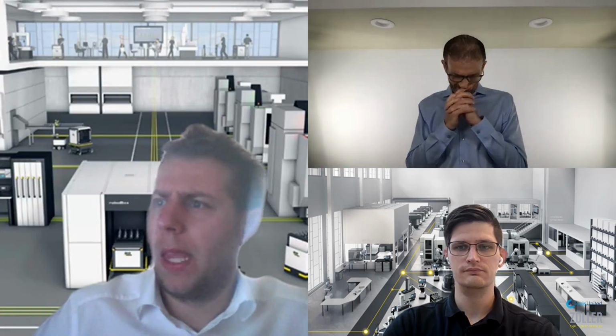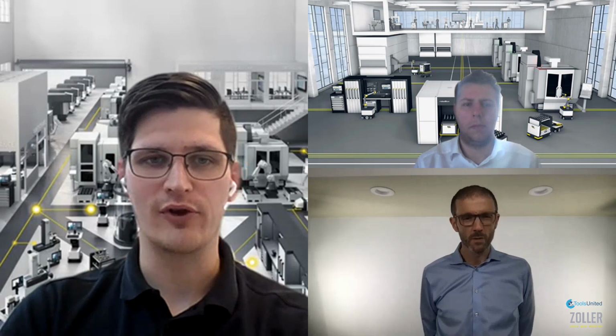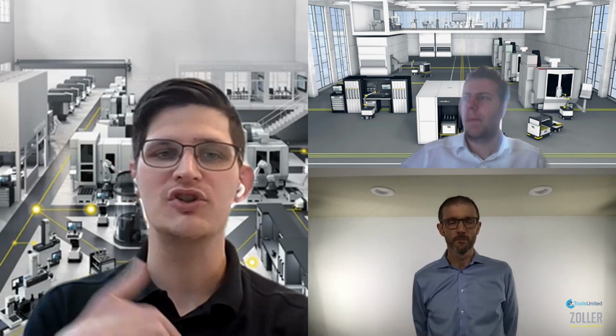Excellent. The next question actually could be for both of you. I'm not 100% sure. The question is, how would this work with already established tool parts, single components? Yeah, I can answer that. So inside Zoller, we have a function for the import from ToolsUnited or ToolLink, which is called update mode. So if there's already an existing component, but for example, the article characteristics are missing and you download that component with the same component ID, it will just override the missing information or will establish these in the database. Very good.